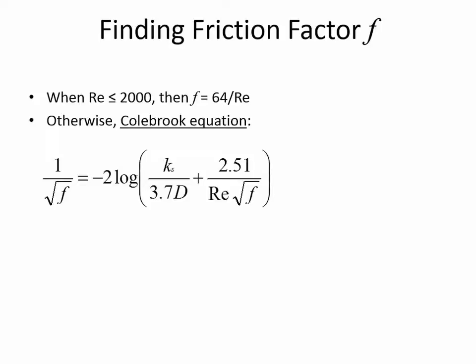In the Hazen-Williams, which you took a look at last semester with that pipe rack lab, the C values in theory should be constant over the range of flow rates. And the same is true of a Manning's equation N value, that the roughness is constant. It does not depend on flow conditions.